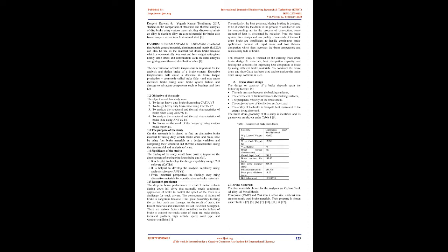In addition to linear/static, ANSYS Workbench performs coupled analysis types, thermal stress, stress modal, thermal stress modal, as well as some limited nonlinear analysis types: thermal with temperature-dependent material properties and convection, geometric/contact with contact supporting liftoff. All solver settings and iteration propagations from one solve step to the next are performed automatically.